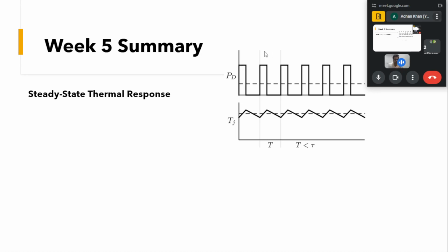That is why this power has been shown as a train of pulses. As shown, if we have a Ts, this loss will be in this time only, and this power loss will comprise the turn on as well as the turn off loss. So let us say in a particular switching instance we had a turn on, we had a power loss.